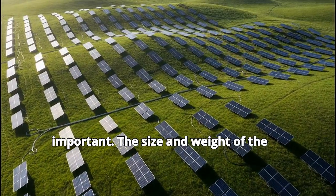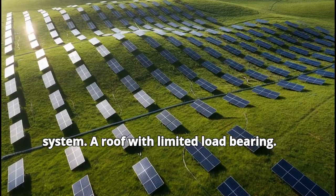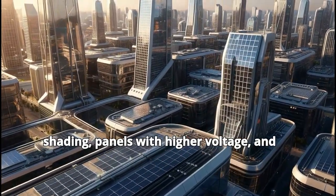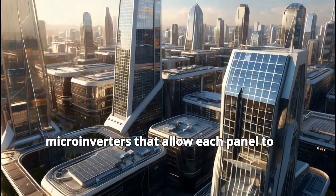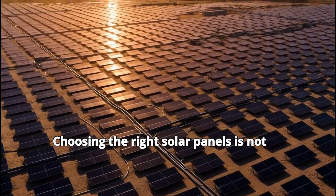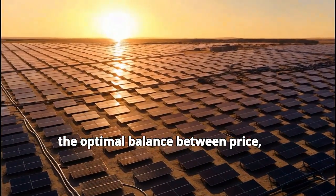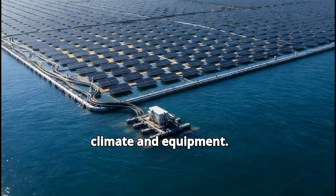Installation is equally important. The size and weight of the panels affect the choice of mounting system. A roof with limited load-bearing capacity may require lighter panels. For roofs with complex shapes or heavy shading, panels with higher voltage, and systems with power optimizers or microinverters that allow each panel to operate independently are better suited. Choosing the right solar panels is not only about finding the most powerful or cheapest panel, but also about finding the optimal balance between price, efficiency, and durability that suits your climate and equipment.